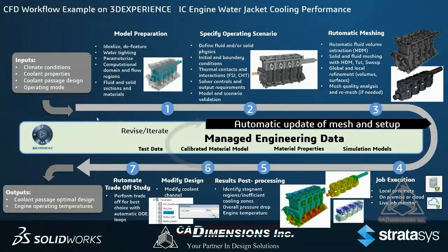From here, once we have our basic mesh, we can do the standard local refinement, right? If I need to refine on a surface or refine at a boundary, we can do that. We can use our mesh analysis tools, go from there. So the process or the principles are the same. The process is just a little bit more automatic on the platform.